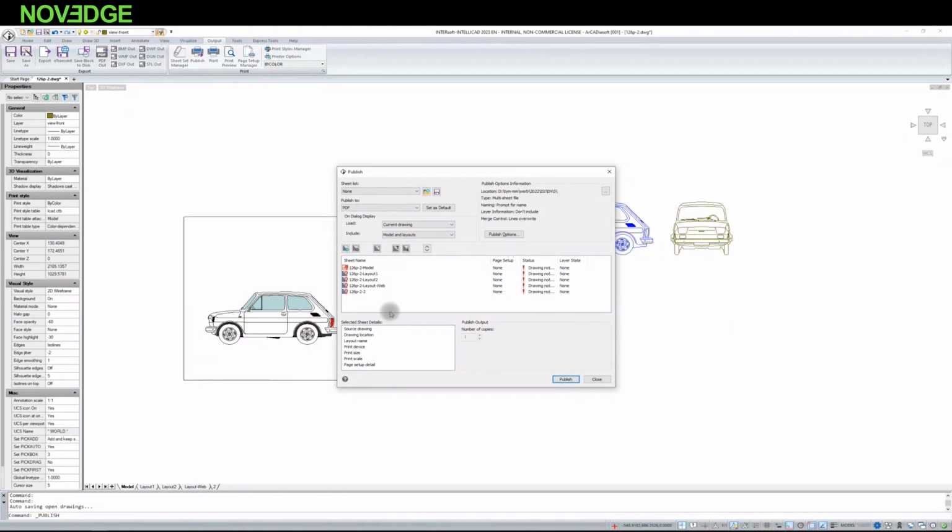I don't want to print these default sheets, but now I can print these defined sheets, show how many copies, and say Print. If something is not correctly defined, for example, if the printer is incorrect, or if we opened a drawing with settings for a different printer than the one we have on this computer, it will be indicated. If there are no errors, we'll be able to print smoothly.